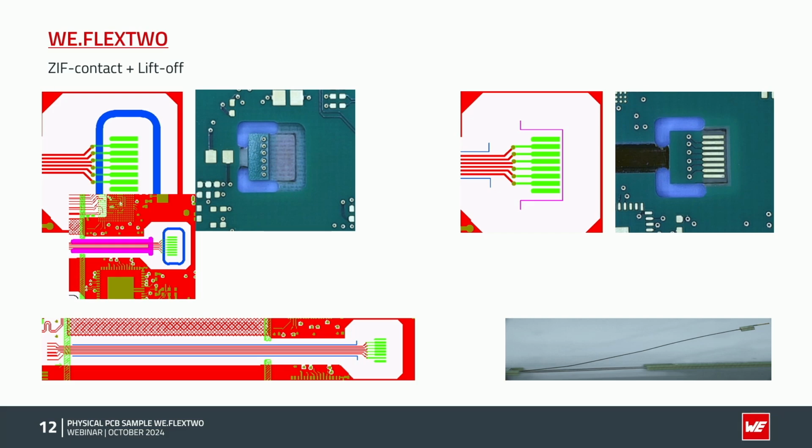So we have dust. And during the layup, it is possible that we get some prepreg dust on the connector fingers, right here. So we have prepreg dust or resin spots after lamination on the copper, and of course, if we have it on the copper, we can't remove it. We have it on the gold fingers as well.